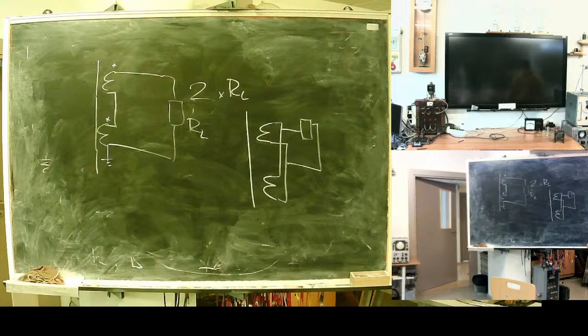Good transformers and good high voltage switches come with a built-in set of current transformers. Next time you drive near a large power transformer, take a closer look at the place where the high voltage insulator goes into the main body, the main vessel. You'll see a kind of adapter, usually a large cylindrical part, between the insulator and the transformer body itself.